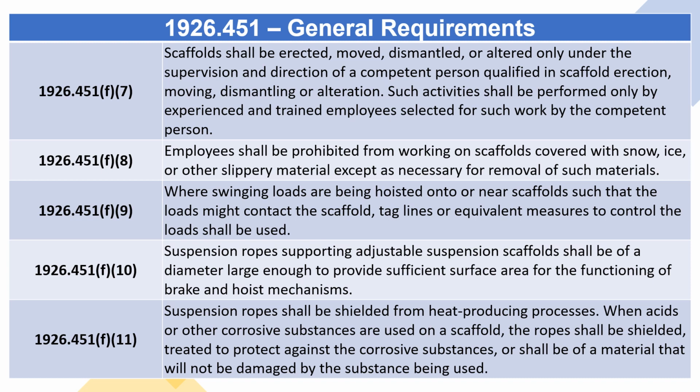1926.451(f)(7): Scaffolds shall be erected, moved, dismantled, or altered only under the supervision and direction of a competent person qualified in scaffold erection, moving, dismantling or alteration. Such activities shall be performed only by experienced and trained employees selected for such work by the competent person.